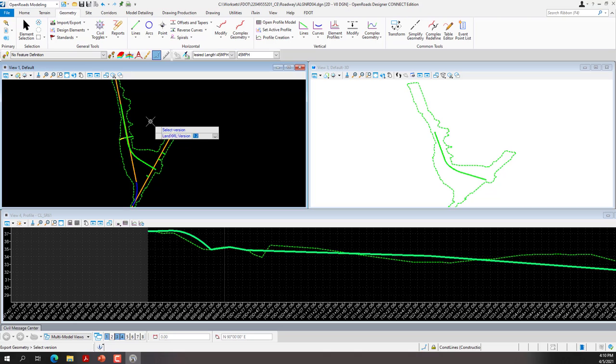It's going to save it as a LandXML version 1.2. So do that, and I'll just left click. Just a note for this tool is saving the only active profiles. That's fine because I have one profile.